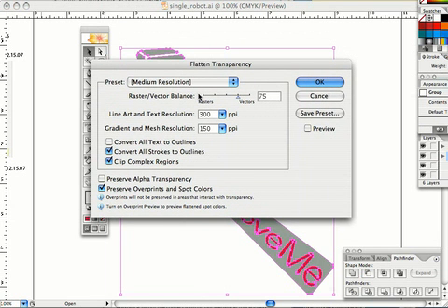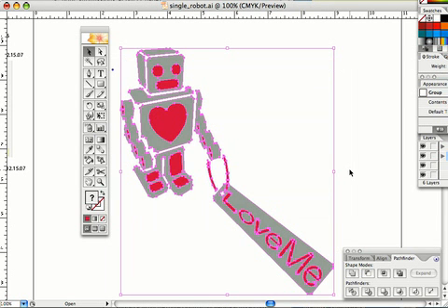And this is actually going to flatten your entire transparency and get rid of all of your outlines and everything, and so they're flattened. So go into your vectors, bump that up to 100, and come back down here and re-click convert all text to outlines. So once you click that, ching.